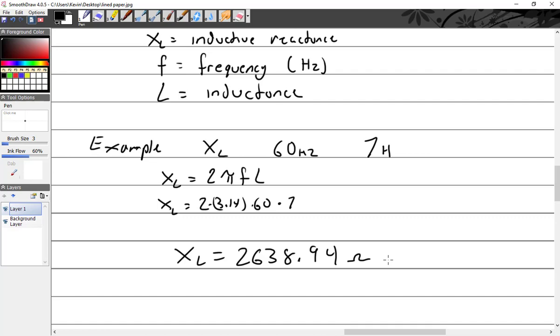Yes. You put, due to phase shift, it is not considered resistance. I'm going to get to this in the end, but with any circuit, just like we did before, we're given a voltage, and we're going to figure out what our total resistance is and what our current flow is. But because of the way AC circuits work, you can't add inductive reactance, X of L, to the resistance to get R total. It's going to be a whole other thing. So there'll be an R total, but it's not the R total you're used to. Because there'll be an R total, X of L total, and X of C total, and those are not going to equal R total. It'll be Z.